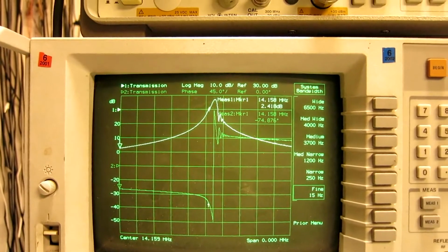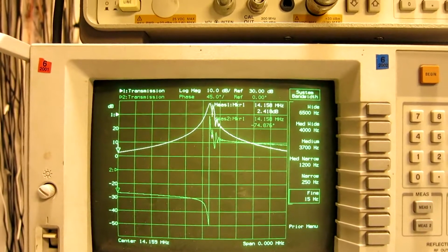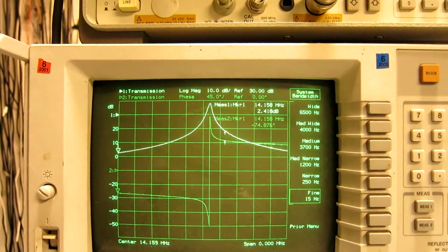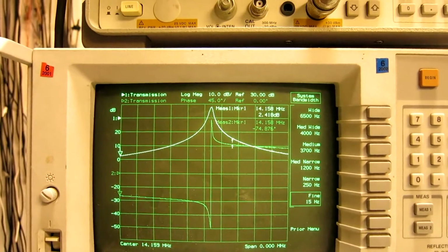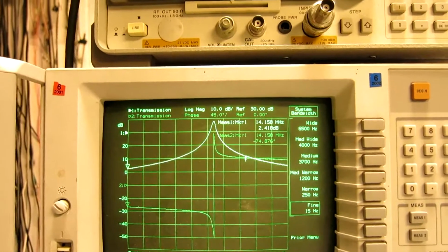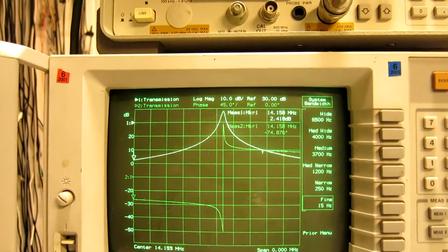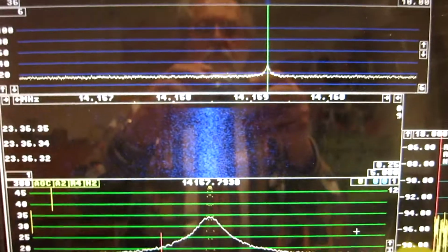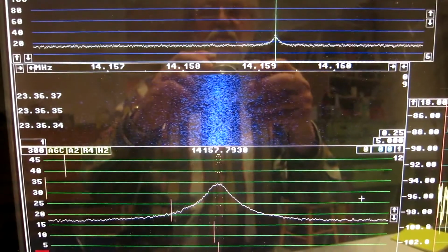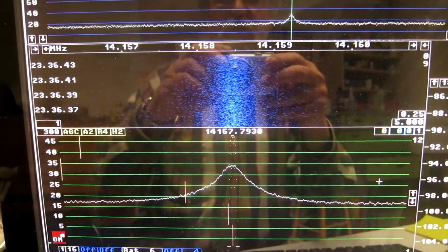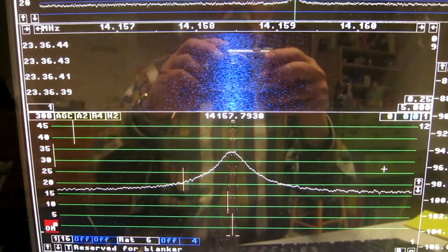And the gain is now, when I sweep slowly enough, you can see it is 38 decibels extra gain because of the positive feedback. The unit is now running as an amplifier. There is no input, this is just the noise on the output.